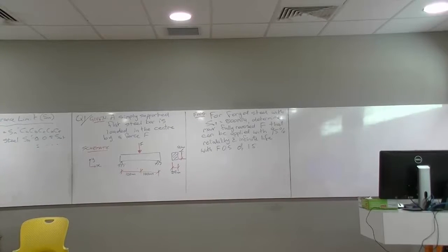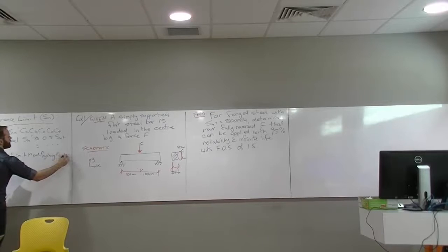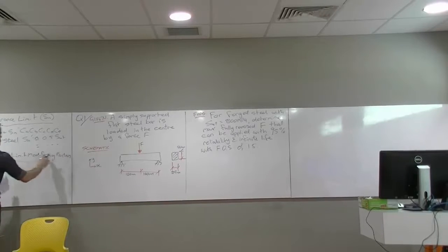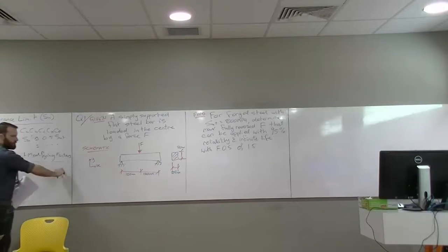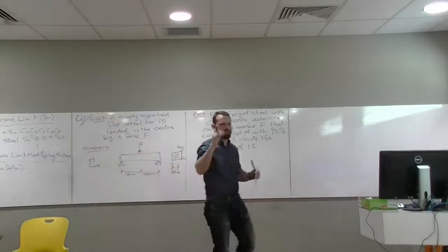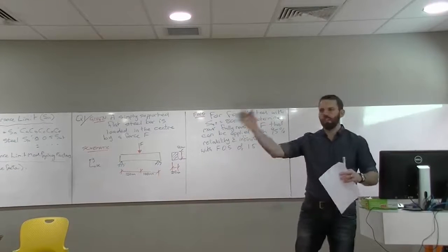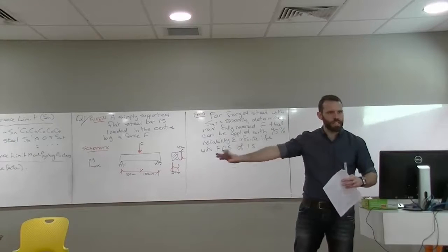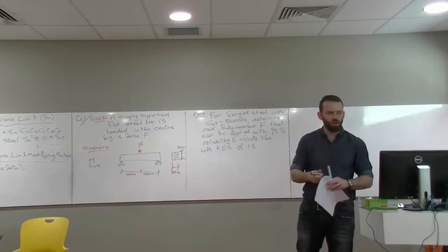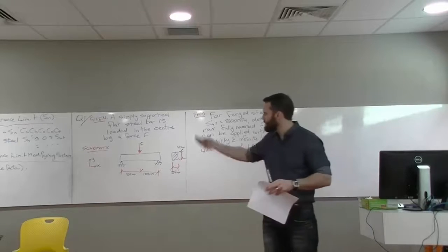And then put a heading for endurance limit modifying factors. And at that point, you can say Ca, size factor, and then any information you need, any assumptions you've made, and the actual calculation for that number, and then Cb, any calculations, assumptions, anything, Cc, anything, and so forth. And at the end, you say Sn equals whatever you end up with.